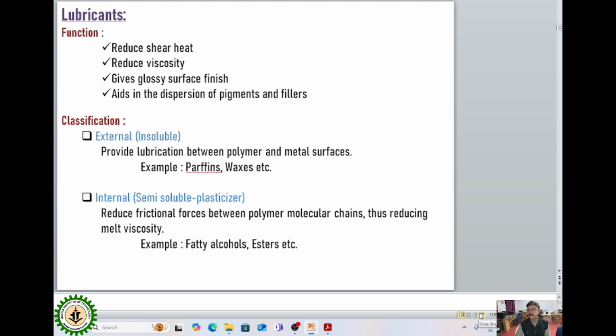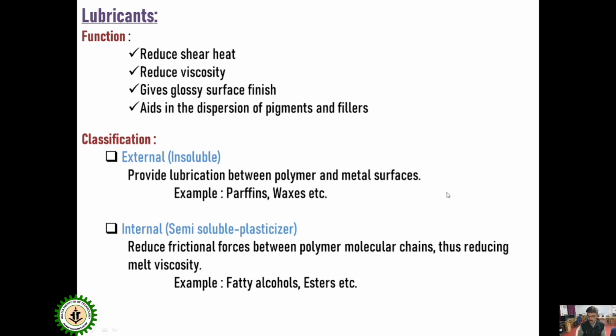Lubricants. The main function of lubricants is to reduce shear heat, to reduce viscosity; they give a glossy surface finish and aid in the dispersion of pigments and fillers. So it also helps to distribute the other ingredients. Generally lubricants are used to decrease friction.